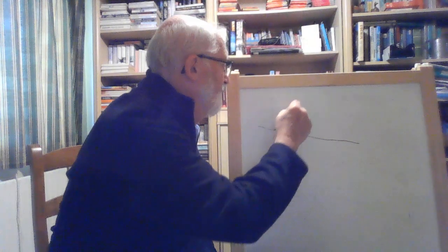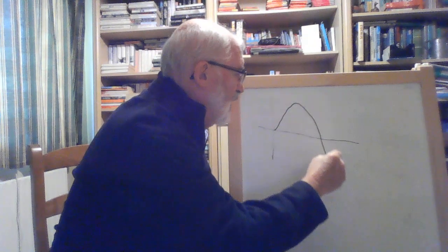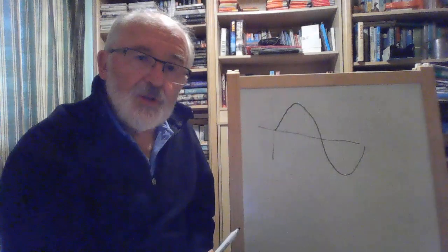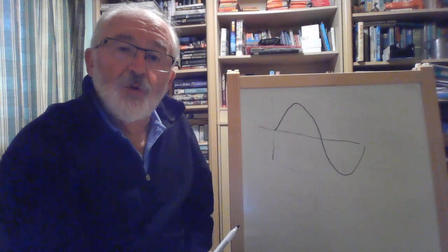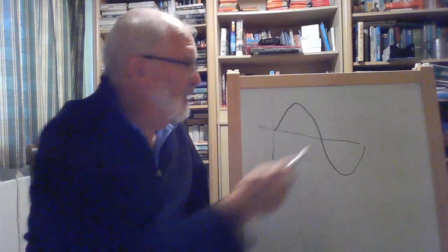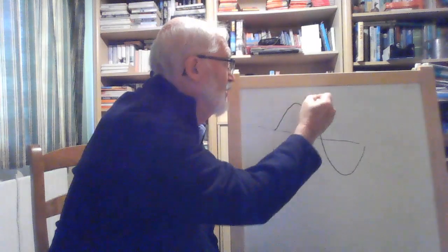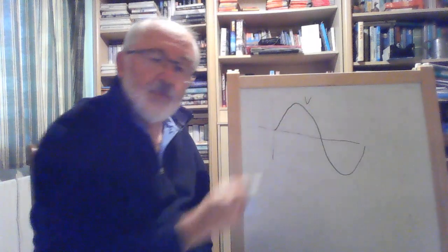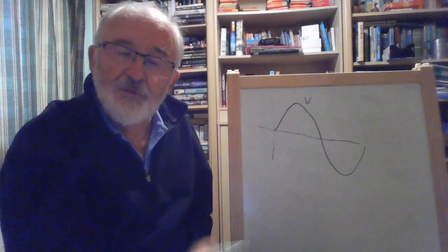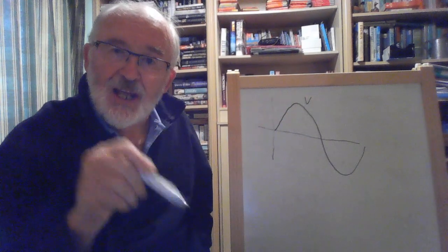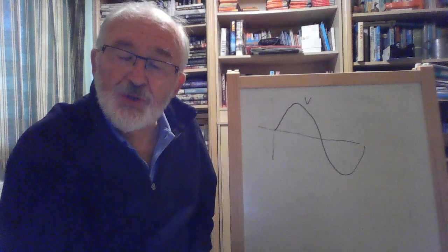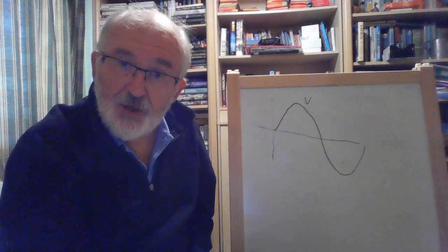So what we get from this is it means that the voltage we generate, there's the voltage in our sinusoidal form. What this means is that for an inductive circuit, this voltage follows that pattern. But as we saw looking at Faraday, when we induce an EMF into a coil or a circuit, we also induce a current.